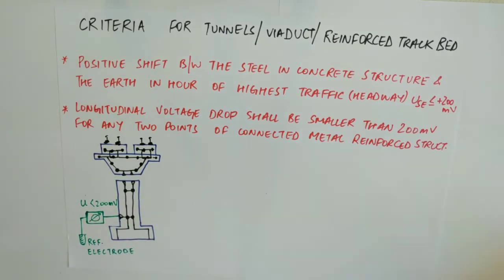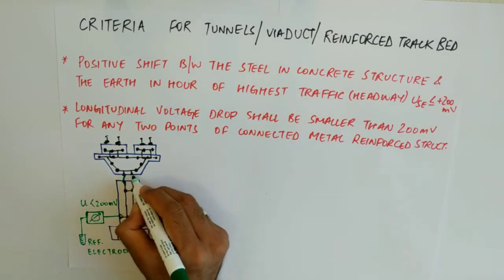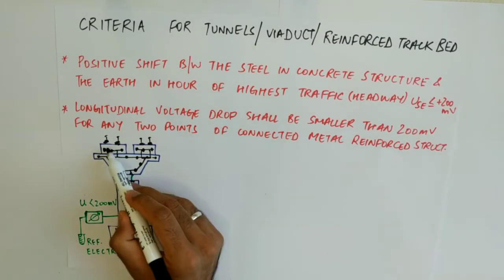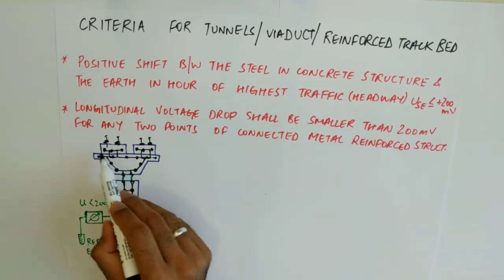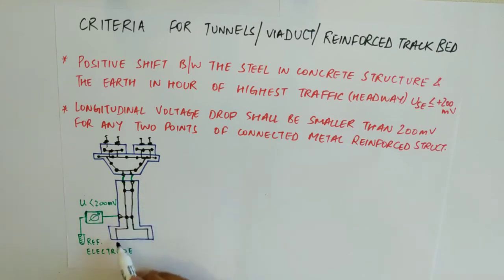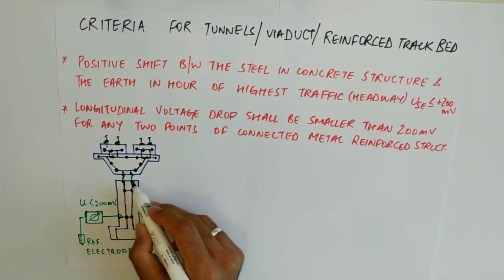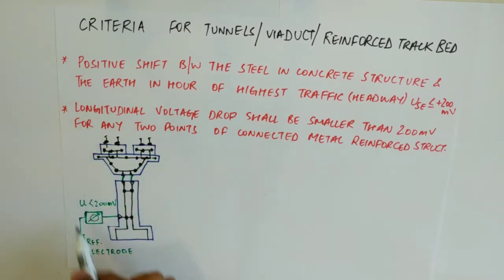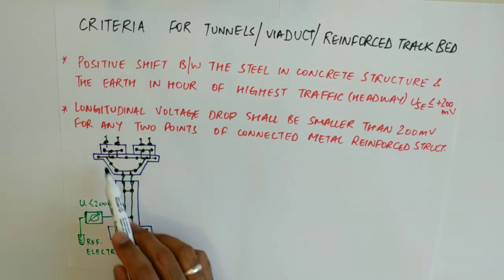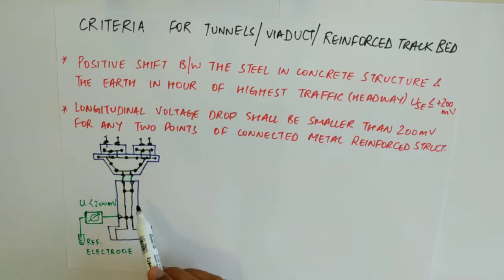So there will be more stray current entering, and it will be going through these rebars, it will enter inside, and some current will be going longitudinally and some current will be going through this column to the earth and to the nearby structures. So these are your dedicated rebars in the pier structure, and they are connected through these earthing cables. We'll be discussing in detail about these systems in the upcoming lectures, how the shear connector has to be connected and all.